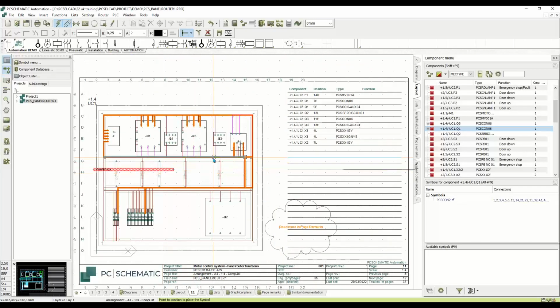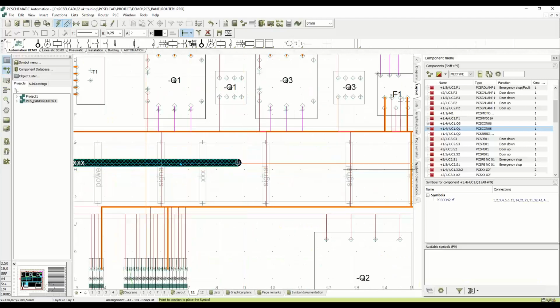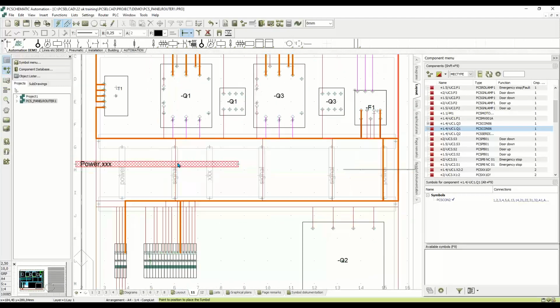So when I go in and say, where do I want to put my wires? I have a few things that I can use. One thing is that I can use those classes, and I think that's a very smart way of using it, because I only want to make sure that I'm not having signal and power in the same trace, or any way that I can control them. So that's what I can do. And that means that the secret is to use those power routing classes. I simply add them to the wires, and then I can subsequently add them to the trace here.